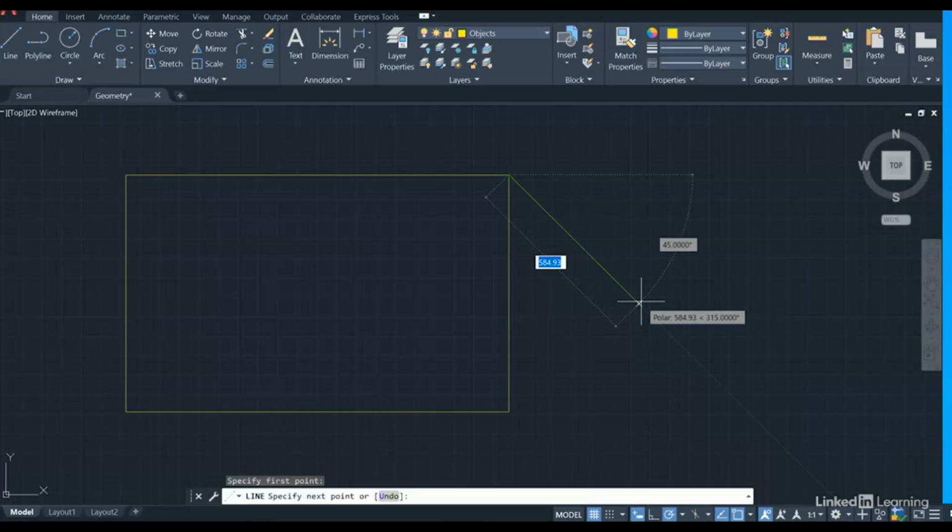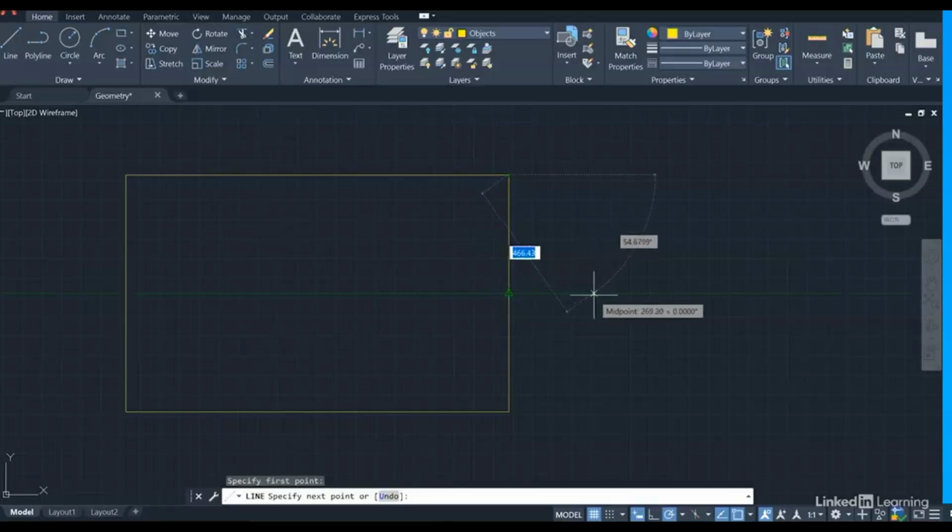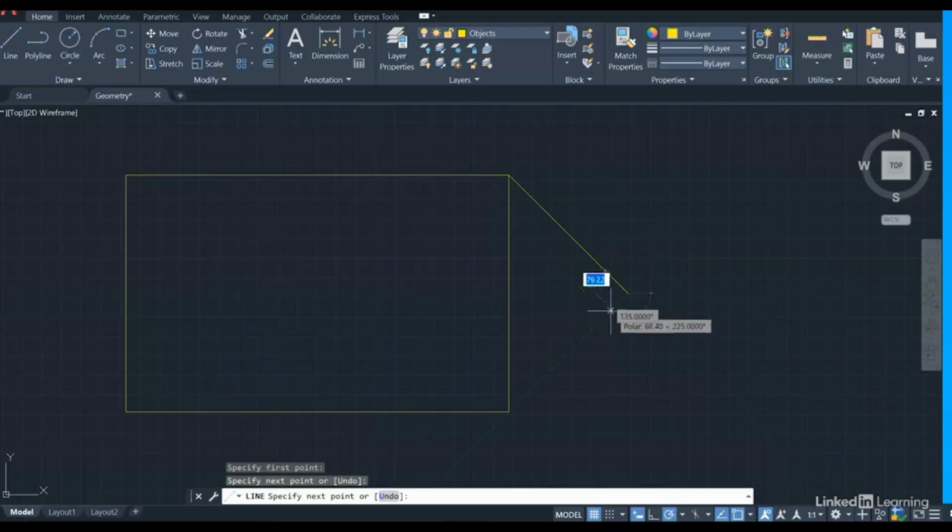Now, I've also got my object snap tracking on. So if I now just hover over this midpoint here on this vertical side of the rectangle, and then just drag out slightly, watch what happens. As I hit that 45-degree line, can you see the polar tracking kicks in, and I also get an intersection there. So I now know that that 45-degree line comes down on that second end of the line directly opposite the midpoint showing there on the left on the vertical side of the rectangle. So I can left click and I know that that's exactly at 45 degrees.